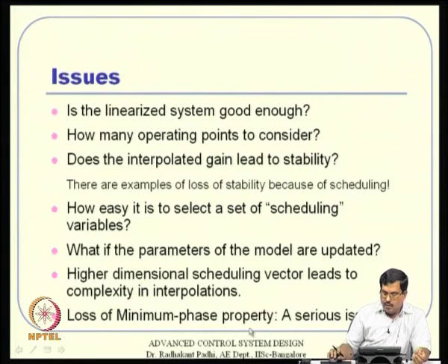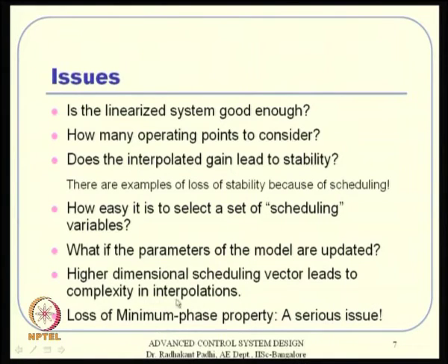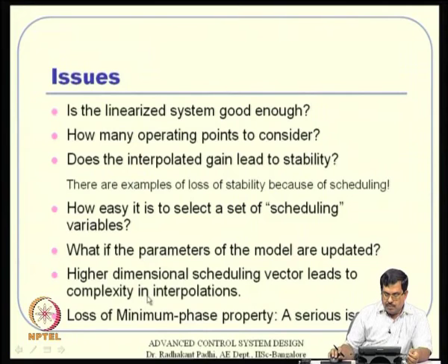And there is a very serious issue called loss of minimum phase property. That means it leads to non-minimum phase systems, for which the zero dynamics or the internal dynamics will go unstable.